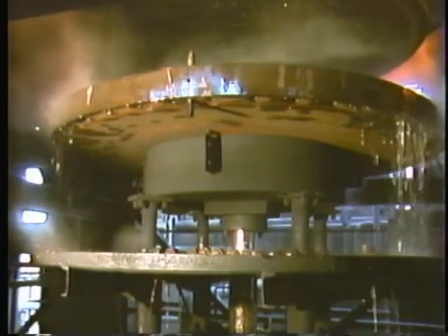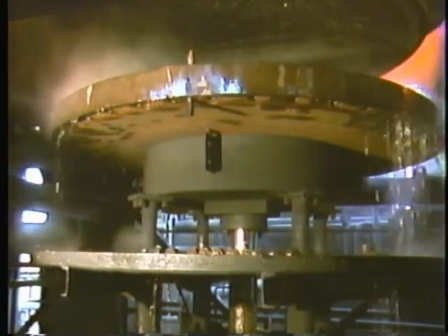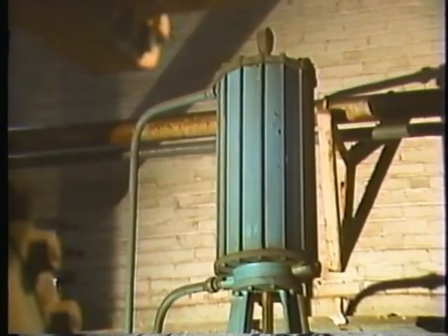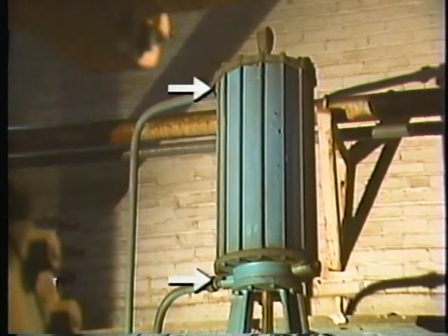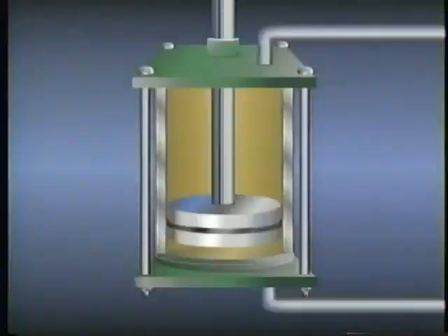We've just seen how fluid flows only to one side of a piston in a single-acting actuator. On the other hand, in a double-acting actuator, fluid flow can be applied to either side of the piston. This is the type we've seen earlier. Let's take a look at this double-acting hydraulic actuator to get a closer look at how this works. Its main parts are nearly the same as the single-acting one. The differences are that the cylinder on this double-acting actuator doesn't have a vent, and it has two fluid ports instead of one. The two ports allow fluid to enter and exit on both sides of the piston.